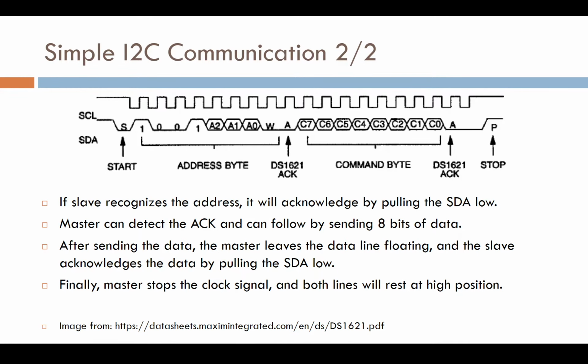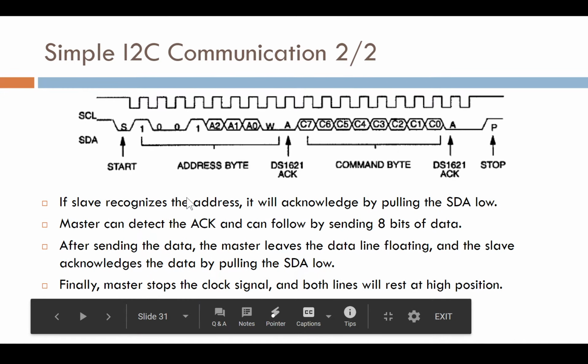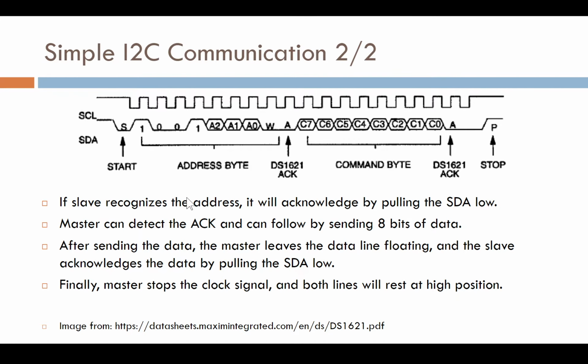Okay, this seems to be okay. It's still telling the same, but with a little bit different details. There's the acknowledgement signal. So practically, when the processor has sent this address byte with the write bit, it waits for one clock cycle. So it reads if any device recognized that address. If there is a device recognizing the address, then that device keeps that acknowledgement bit there during the clock cycle. Okay. So this way the sender, in this case the processor, knows that the data transmission went okay.